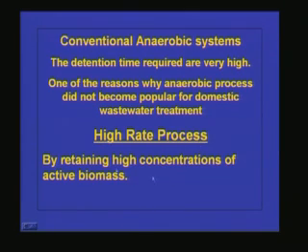In high rate processes, the system is able to retain high concentrations of active biomass. That means the microbial concentration in the system will be very high. We have seen that the regeneration time or reproduction time of anaerobic bacteria, especially the methanogens, the methane producing bacteria, is very high. If the reproduction time is very high, naturally the biomass concentration will be very less.